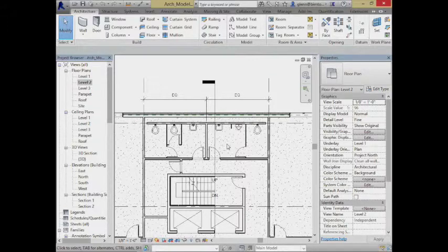Let's talk about these systems a little bit and what the design is like behind them. You'll notice even in this floor plan view, as we look at these bathroom spaces, that I have 2 walls set up right now. I have an inner wall and an outer wall. This is very common, especially in commercial construction, because we don't have enough room in the wall itself to accommodate all the pipes. So we set up an interior wall and a little bit of space to accommodate the pipes and everything that needs to happen mechanically to support these fixtures.